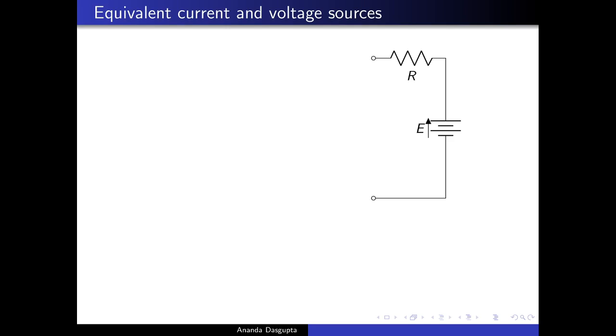The answer is no. If your circuit has a very, very high impedance, that is, it draws very little current, ideally if it draws no current at all, then the voltage delivered by the battery is exactly equal to its rated value, the EMF. On the other hand, the more current the external circuit draws, the less voltage does the battery deliver. So the battery voltage drops as the current delivered to the external circuit increases.